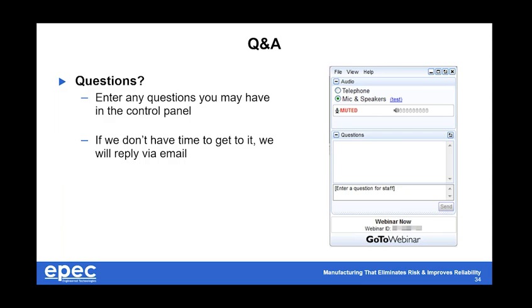Next question, can we add our company name and logo to the wire jacket and still satisfy the UL requirements? So one of the issues we run into here is when a customer wants to completely strip out all the part markings and only have their company logo or their brand. This would violate UL. Per UL, we have to have the UL number itself, the flammability rating, temperature, voltage, etc. So those must be there.